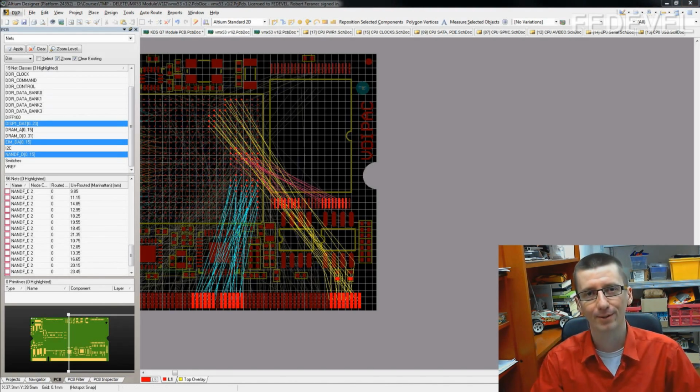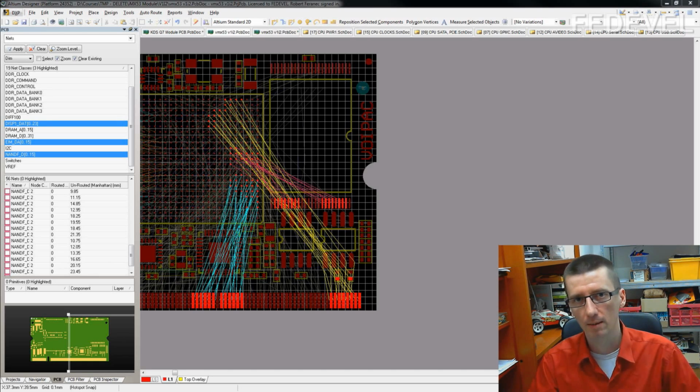Now you have it, you spotted it. I don't do layout based on pin-to-pin connections. I do layout based on buses, based on groups, based on interfaces. So when I do layout, I do layout for the whole PCI bus, for the whole ISA bus, for the whole display.